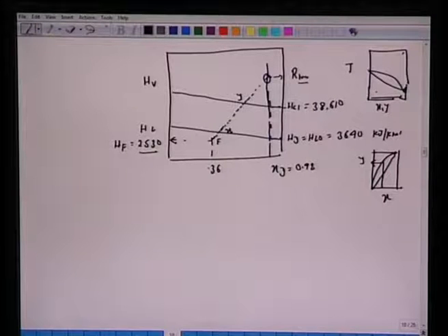Now as we said earlier, in some cases it's possible that some other tie line might give us this R min. But in this case, when the curve is concave downward like this, we have shown here that this tie line passes through this feed F. So we know R min. From this we can measure this segment divided by this segment, which will give us R min.